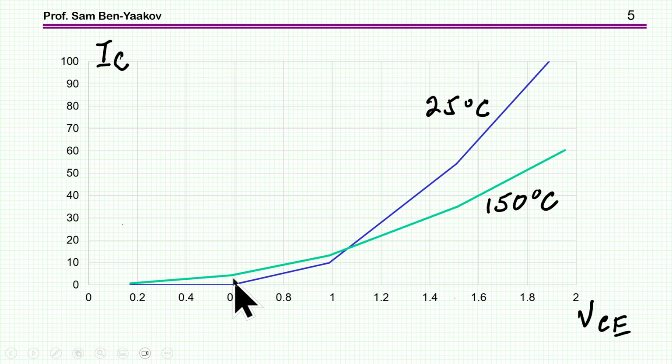It's a phenomenon that you can see in IGBTs, and you can see it also in MOSFETs, in fact. The crossing point could be here, and it could be much higher, which is very bad. We'll see that. So having it at a low current is better, and I'll explain it later on.